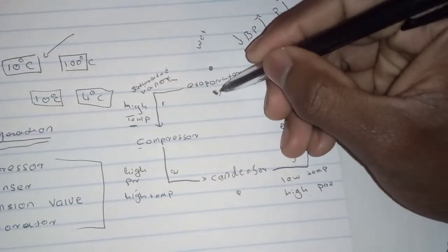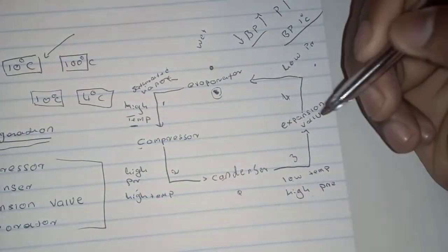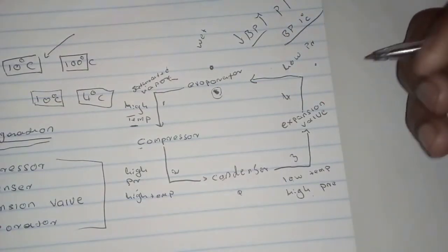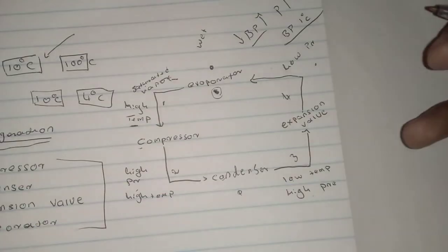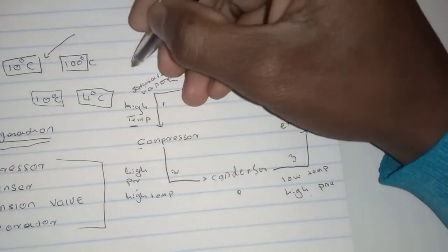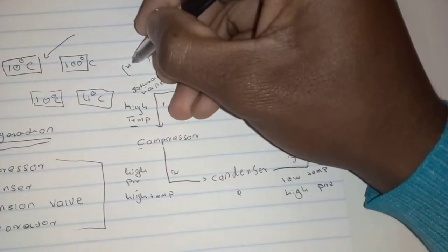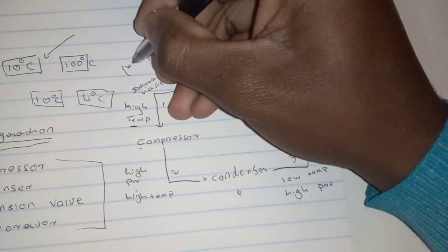So absorbing the heat energy from the object that we want to cool will cause the refrigerant to continue that phase change up until it gets maybe to a state where it is dry saturated or superheated, which are the conditions that you can have here. You can have the refrigerant as wet steam.